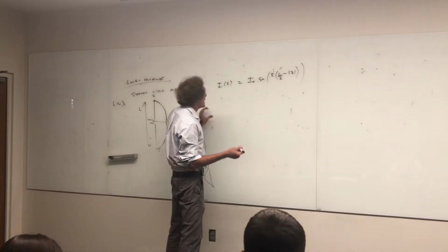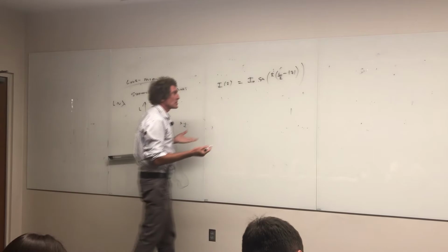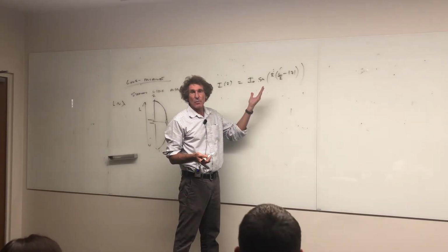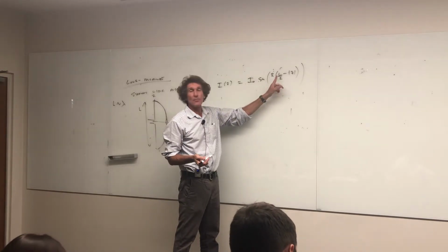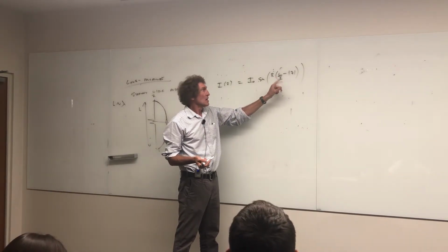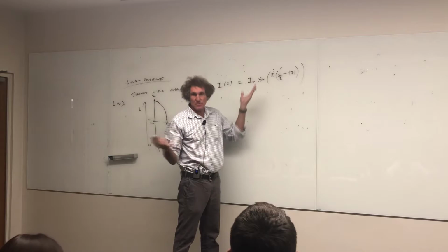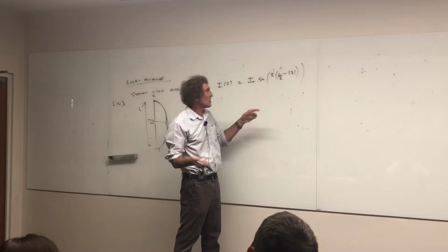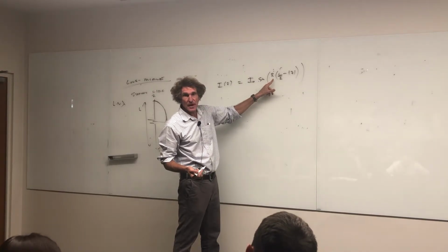So if that's equal to I of z, you can just think about what happens. Well, at the end of the wire, you're at plus or minus L over 2, right? Well, that means this is 0. The sine of 0 is 0. It goes to 0 at the ends of the antenna. Do you follow me? Then based on what beta is here, you can find the value at z equals 0.